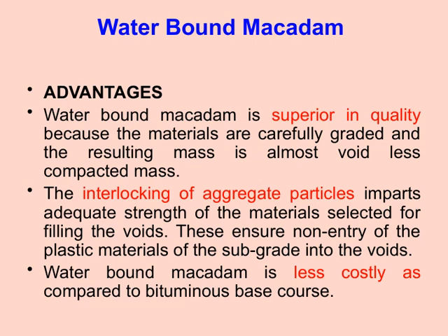Water-bound macadam is considered superior in quality, and that's mainly because of the way the materials are carefully graded before use. When we compact the mixture, it forms an almost voidless mass, which is crucial for durability. The key here is the interlocking of the aggregate particles. This natural locking provides the necessary strength for the road, making it quite resilient. Plus, these interlocked particles help prevent the plastic materials from the subgrade from entering the voids, which can otherwise cause issues later on.